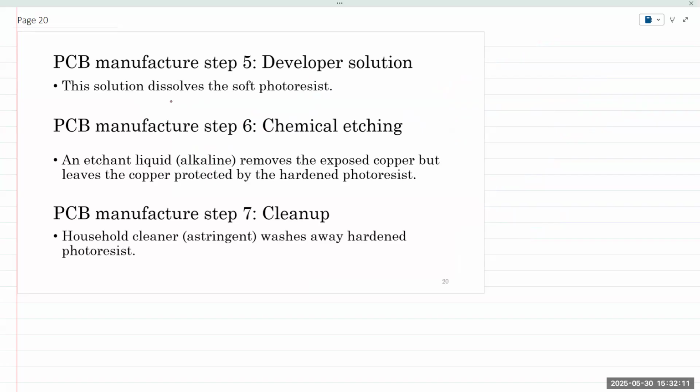So you have copper, and you take like a big beaker. Our PCB was this big. And we take ferric chloride. I still remember, somewhat like dirty yellow in color. Ferric chloride chemical, you put it in a bath, mix it with water, create your solution, and you stick your PCB in there.